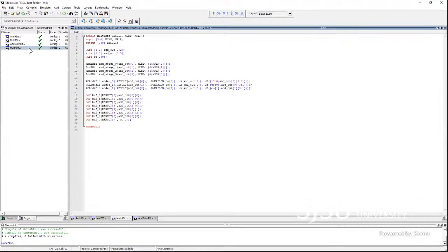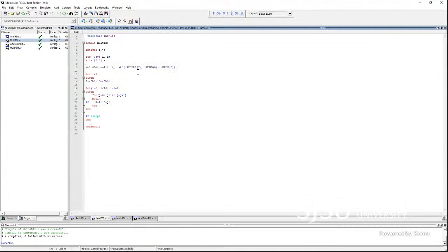On the testbench side, very simple, we instantiated that multiplier and are simply multiplying 0 to 15 with 0 to 15 in a loop, testing all the numbers in between, and we'll look at the sample result and make sure they're correct.